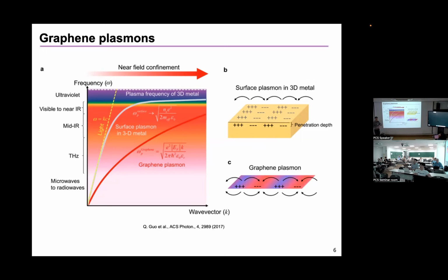We simply think this structure is very thin, so it is very hard to get high electron density. We want to use this 2D material as a photonic device, but there are limitations to getting large electron density or large surface plasma frequencies. So there is a limitation of 2D material-based plasmonics.